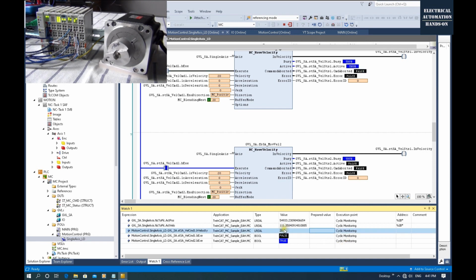So we can see the axis will not reach 300. It will directly go to 20. It does not need to reach 300 first and then go back to 20. So we can change the speed up and slow it down. The actual command to the axis can change on the fly.